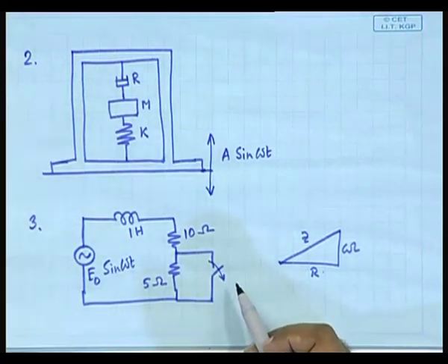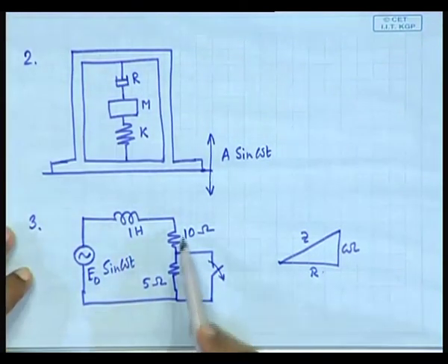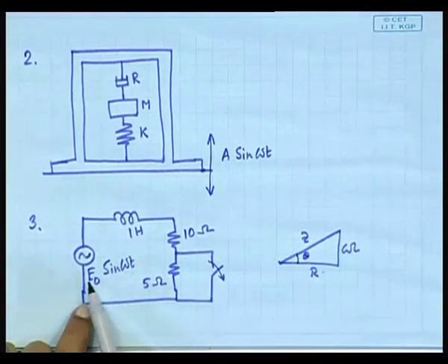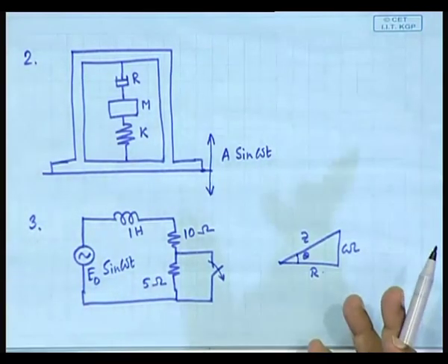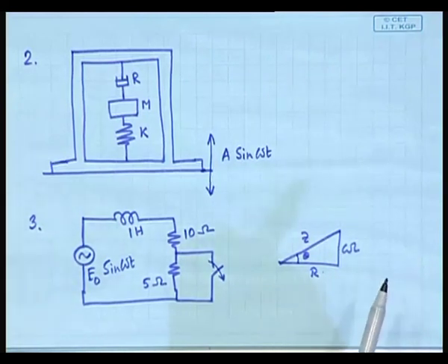We already know that you have to open it where the sinusoid is exactly at, if the new circuit, here it was 1 Henry, it will have a particular omega L. Now the R is 15. For that circuit, whatever is the theta, if this one is opened at that phase angle, then only it will have no transient, else it will have transient.